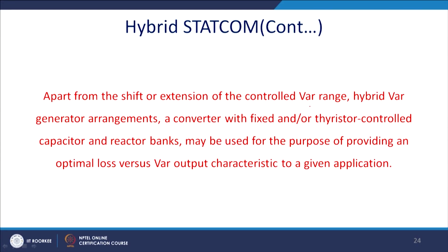Apart from the shift or the extension of the controllable VAR range, a hybrid VAR generator arrangement, a converter with the fixed or the thyristor controlled capacitor or reactor banks, may be used for the purpose of providing optimal losses versus VAR output characteristics for a given application, because switching losses in this case will be lower. So, we can design optimally what will be the solution for it. Some portion which dynamically changes will be in the Statcom and some portion can be fixed. This is a typical design problem for the FACTS engineers.